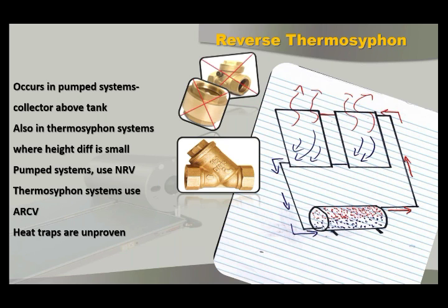A lot of people have their own theories, and I know that a lot of people say different things. The thing about a non-return valve is that it needs to be a spring-loaded non-return valve, because we're talking about a pump with enough force to open that non-return valve properly, and once it's not pumping, we need sufficient force to close it effectively. And once it's closed, it may not then start to reverse thermosiphon.